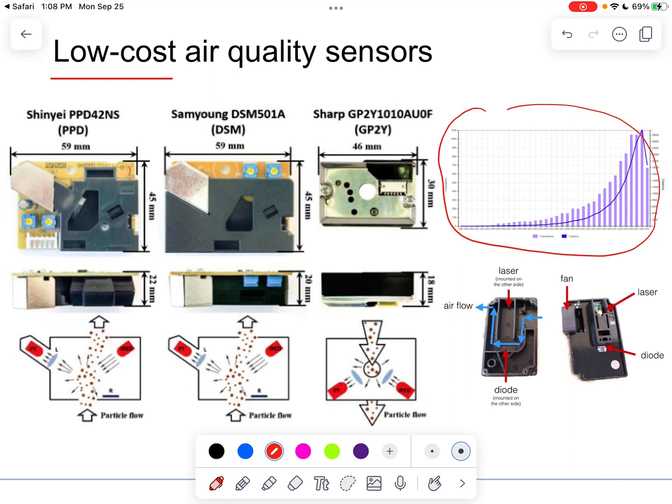So as you can see, because of that, people created different types of air quality sensors. And I would say most of these air quality sensors are using light scattering methods. So here I'm showing you 3 different types of light scattering sensors, or low-cost sensors. You can see they all involve some laser module here. And actually they're using an infrared LED, just light, typical light bulbs. And then the aerosols are being introduced through the sensors, right? And then there's a photodiode that's aligned at a different angle. So if it's placed at a different angle, then it's collecting the scattered light signal.